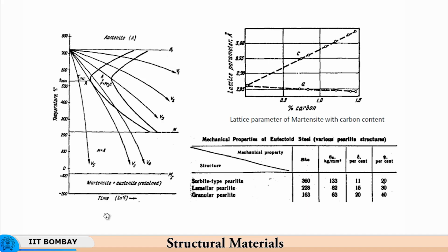So, even if you continuously cool the material to room temperature and martensite start is just below the room temperature, there is no issue, no martensite is formed. Only the austenite phase will be formed, and that austenite phase will be relatively soft. Now when this material is worked, it starts becoming hard very rapidly. Why?